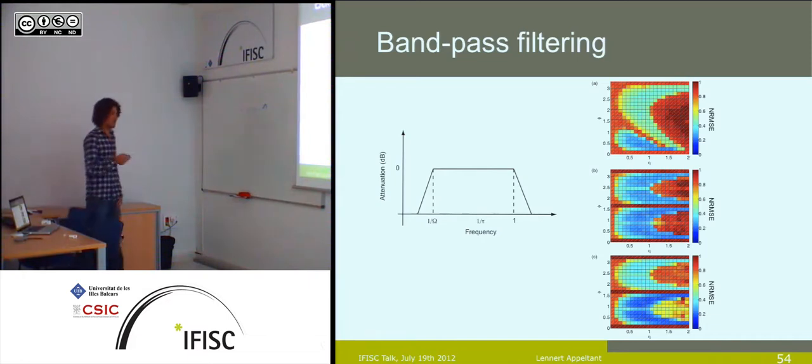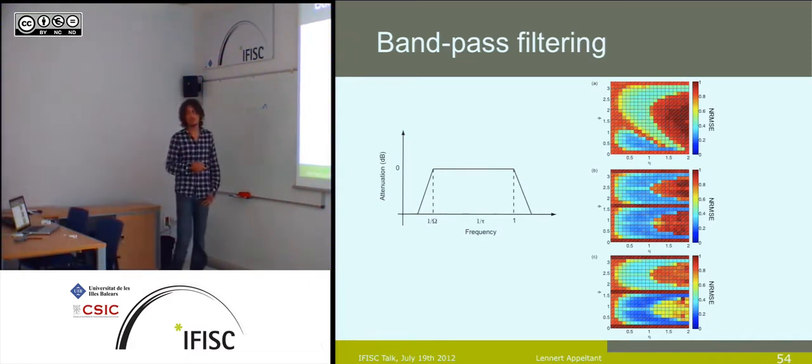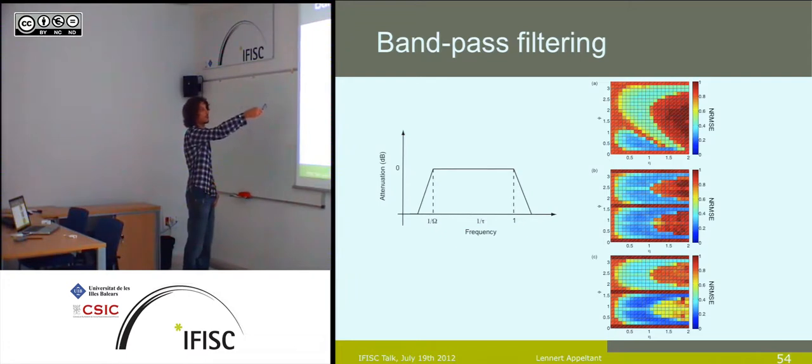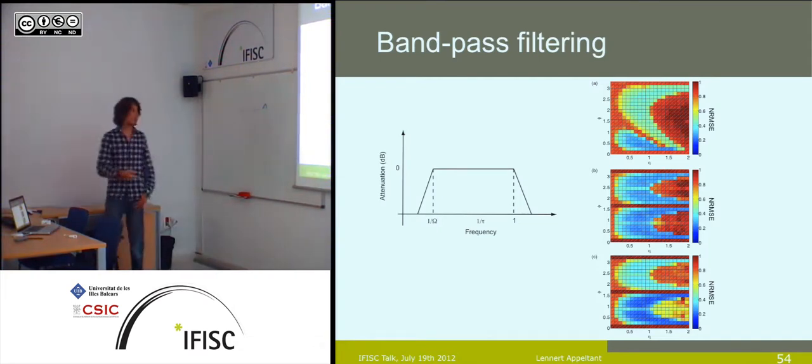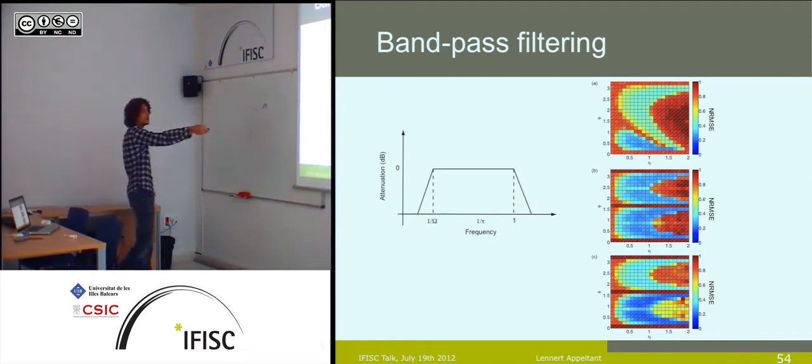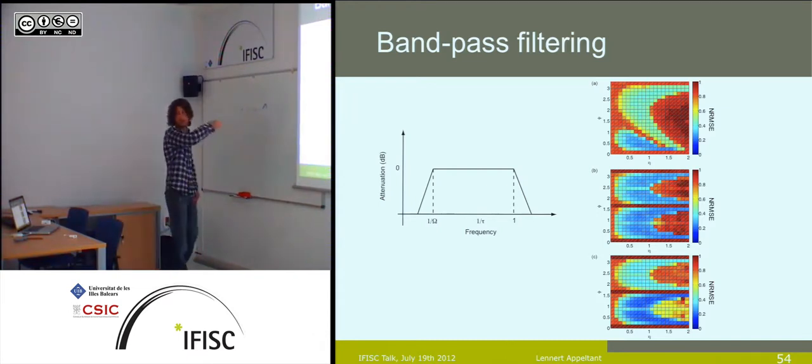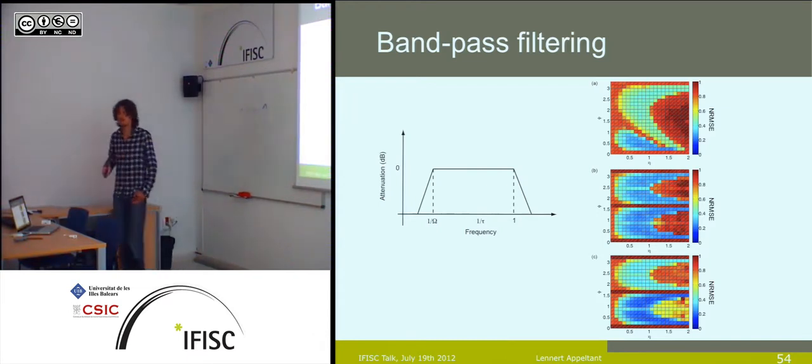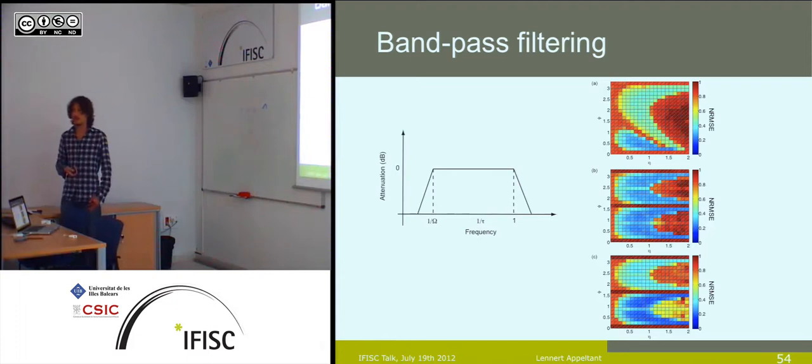Then let's go to the bandpass filtering effect. Because up until now, we had only a low-pass filter. So we were not attenuating all the low frequencies, we just had something like this. What you see here is what I previously referred to as the internal time scale of my node. What you see here is the frequency corresponding to the delay line, and this is the new cutoff frequency that I introduced. I will filter out all the DC, because this is what quite often happens in experimental setups.